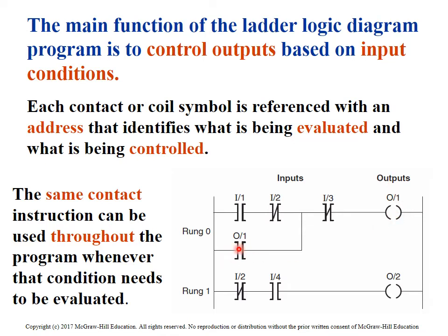which will turn this guy on, and the continuity for that output will stay on, even if you remove these two switches. So if you were to turn this one off and this one on, it would still be on. It would stay on until what? We hit I3. At that point, when we pressed I3, it would turn off. Very common circuit.